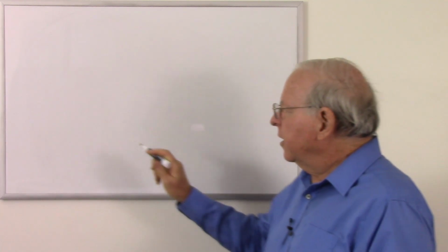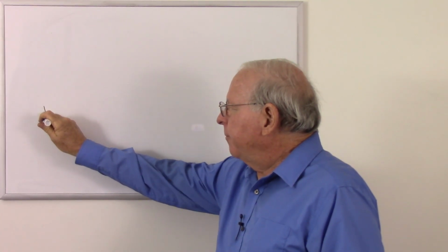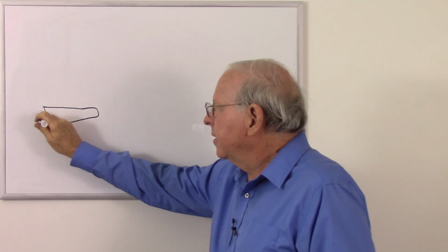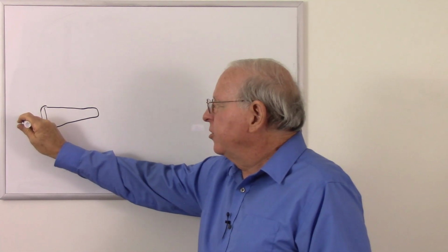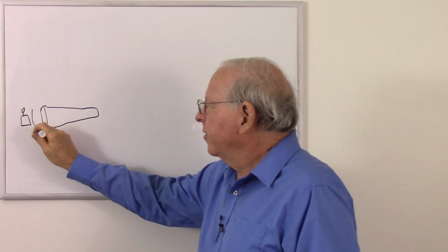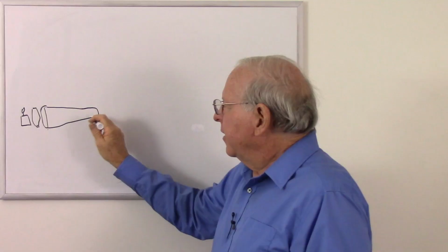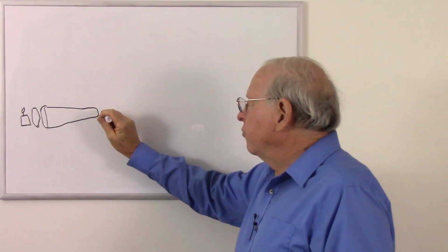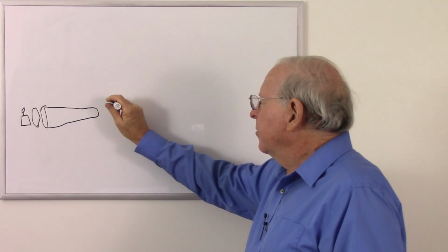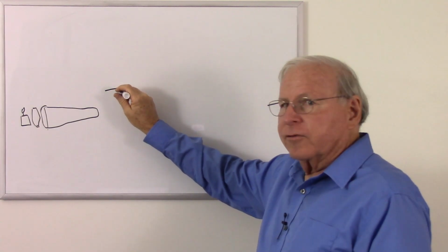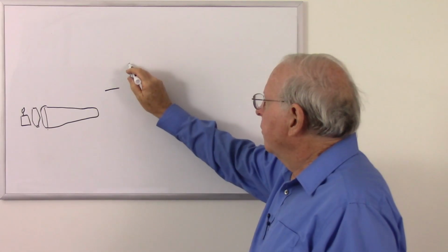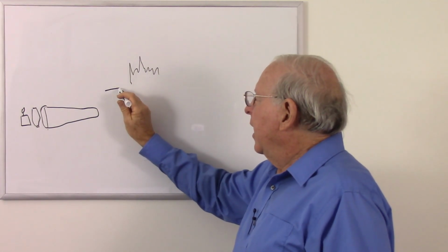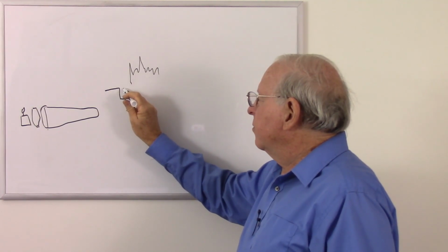So let's review real quickly the whole idea that we had a camera tube at one end of our system on which we were focusing an image through a lens. And this had a mechanism to scan that image electrically and turn that into an electric signal, which looked something like this. We had a voltage which represented black. We had higher voltages that represented a certain amount of light being scanned across, and we had a pulse that went down to 0 volts and back up.